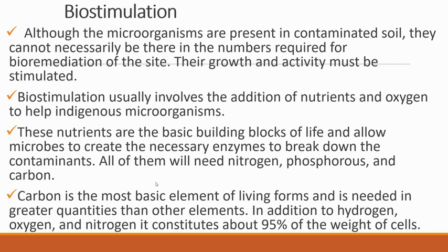So in biostimulation, we add nutrients, maybe in form of nitrogen, in form of phosphorus, to break down the pollutants. These nutrients are basically building blocks of life and allow microbes to create the necessary enzymes to break down the contaminants. All of them need nitrogen, all of them need phosphorus and carbon, and to some extent sulfur.